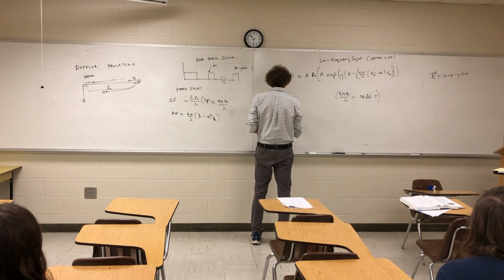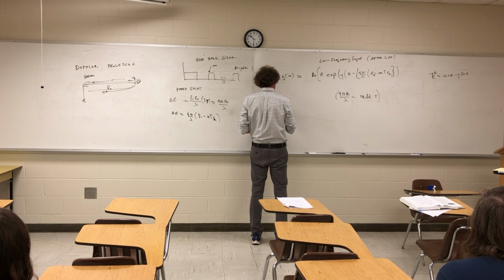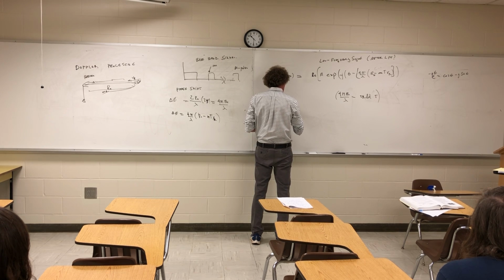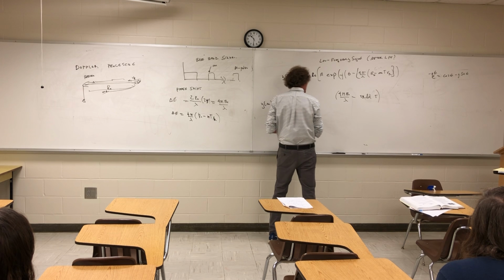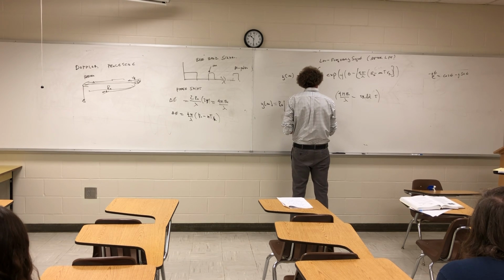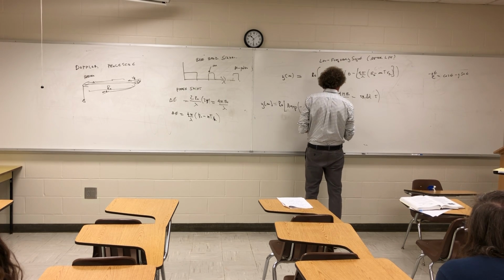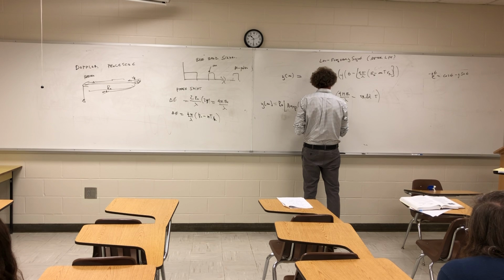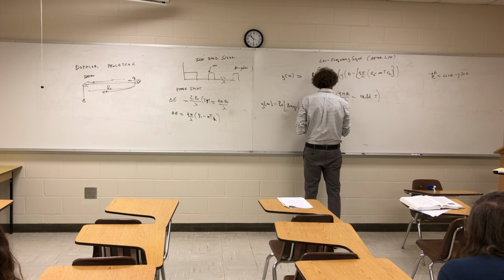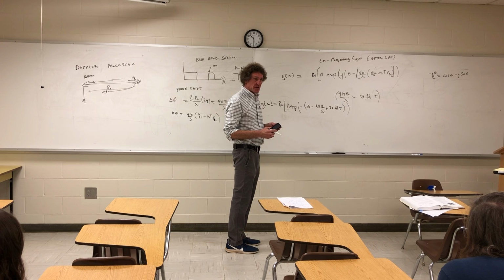Now that's going to be equal to, and this is the low pass filtered version, by the way, get rid of that A. It's going to be the real part of A exp, the minus the quantity of theta minus 4 pi R naught over lambda naught, and then it's going to be plus, because it's this minus that, plus 2 pi F Doppler times the period t. With me on this, guys?